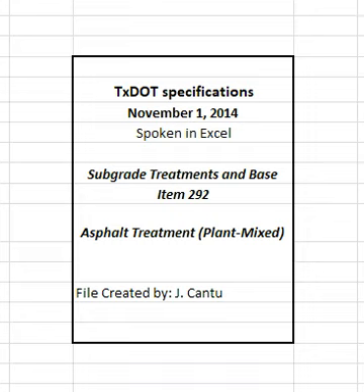4.6.1.2 Asphalt binder sampling. The engineer will obtain at least one 1-quart sample of the asphalt binder used during the project, labeled with date and time, sampled from a port located immediately upstream from the mixing drum or pug mill. The sample will be taken in accordance with TEX 500C, Part 2.